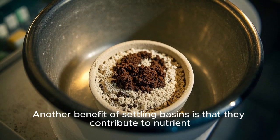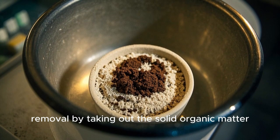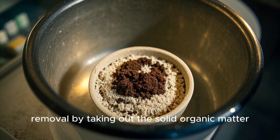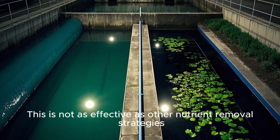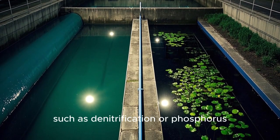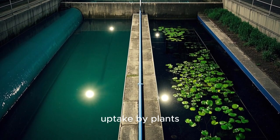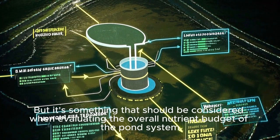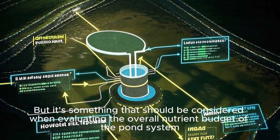Another benefit of settling basins is that they contribute to nutrient removal by taking out the solid organic matter, which contains nitrogen and phosphorus. This is not as effective as other nutrient removal strategies, though, such as denitrification or phosphorus uptake by plants. But it's something that should be considered when evaluating the overall nutrient budget of the pond system.